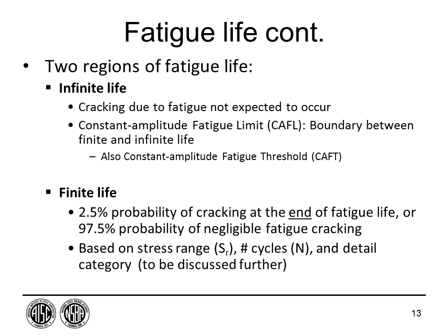We'll talk a little more about what this means in terms of the likelihood of cracking. Fatigue is looked at statistically. The reason is, we'll see, there's a lot of variability in the data. If I have 10 identical tests, I can have, well, I shouldn't say completely different answers, but a lot of variability in the life. Same specimen, same stress range, but a lot of different life. That's because of the things in a specimen, or in real components, that are hard to quantify. And we quantify that based on the stress range that I'm applying, 5 KSI, 10 KSI, whatever, and then how long the test runs. We'll talk more about that.